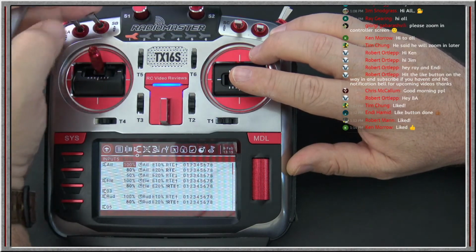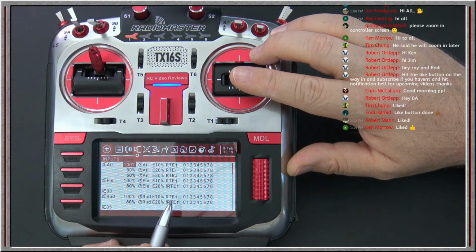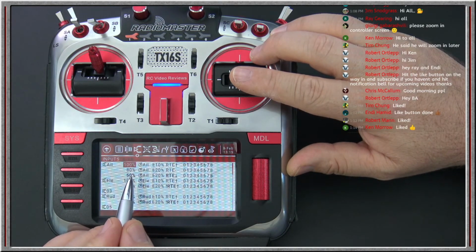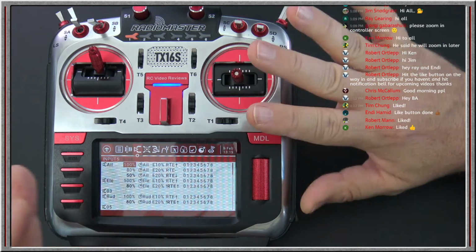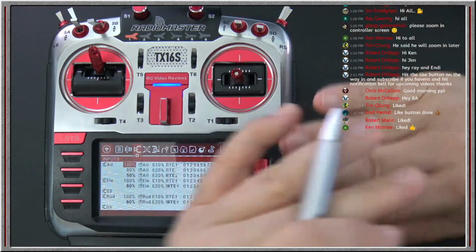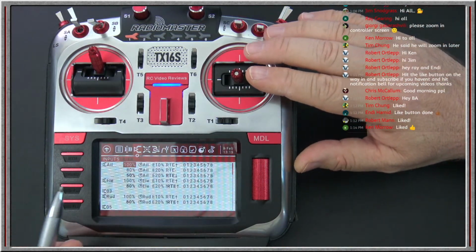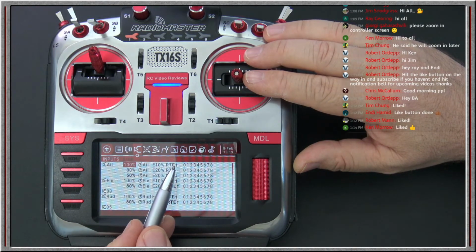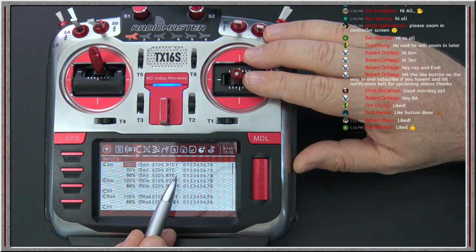Now if I move it down to the bottom position, it doesn't change because the option is anything but up. But notice the aileron did change. See, that's the beauty of using inputs. OpenTx doesn't care. You just have to be specific about your configuration. So I have aileron high defined with up, aileron mid defined with middle, and aileron low defined with low.